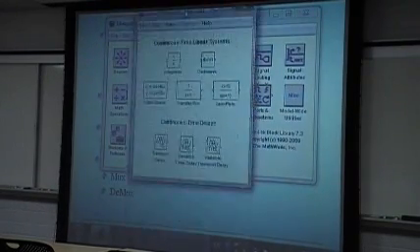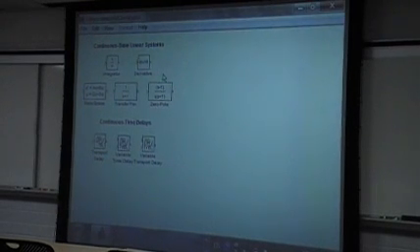And in this group we have linear transfer functions, state-space descriptions, and zero-pole-gain descriptions of systems. We can also easily describe time delays. We have a constant time delay, and also a variable delay. If you are using a variable delay, then it is easy to model, for instance, network control systems, because the delay is usually random, so we can assign a random signal to describe the delay time, and then a random delay is generated. This is useful for network control systems.